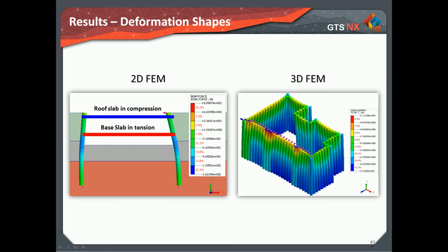And suggested limit equilibrium results look less drastic, though they have not been calculated incorrectly. It is worth noting that analysis of half section in 2D finite element analysis would not have predicted this asymmetric behavior either. This figure on the right illustrates the displacement shape in 3 dimensions and the location with relatively higher displacement due to moment load applied by the columns. Limit equilibrium method is not capable of modeling this at all.